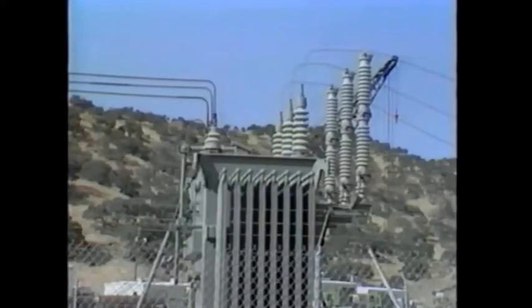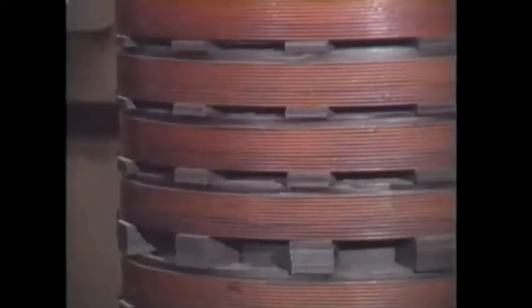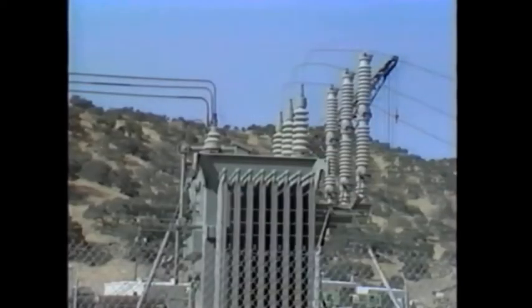Generally, power transformers are three-phase. That is, the primary and secondary windings of each phase are wound on 3 legs of a common iron core, all immersed in the same tank of insulating oil. Single-phase transformers are also used, connected to form a 3-phase bank. Any combination of Y or delta connections can be made to give the desired voltage levels and phase relationships.